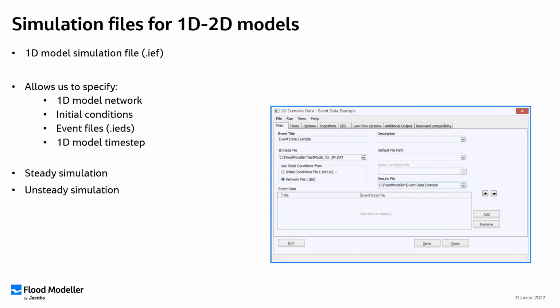The unsteady state solver uses the Preissmann implicit scheme to solve the equations for free surface flow based on the Saint-Venant equations for flow in open channels. This solver provides various features which have been specifically designed to improve model performance and management capabilities. The unsteady state solver allows the model to estimate stage, flow, and velocity through time along the river channel throughout your simulation.